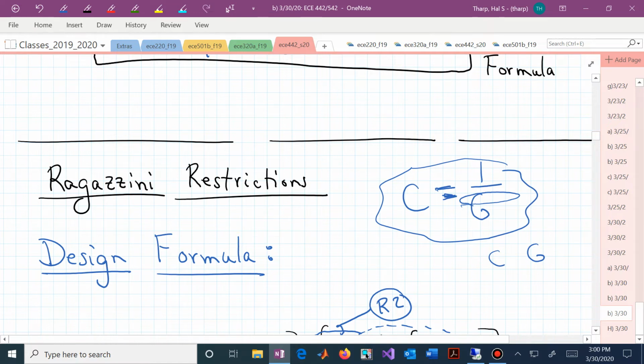And here we're saying, if we just had 1 over G, then whatever was unstable here is going to be canceled by what's now in the denominator of our controller, and the polynomial in the denominator of G is now going to be up here as a zero, and that's going to cancel the unstable pole factors in our original plant.